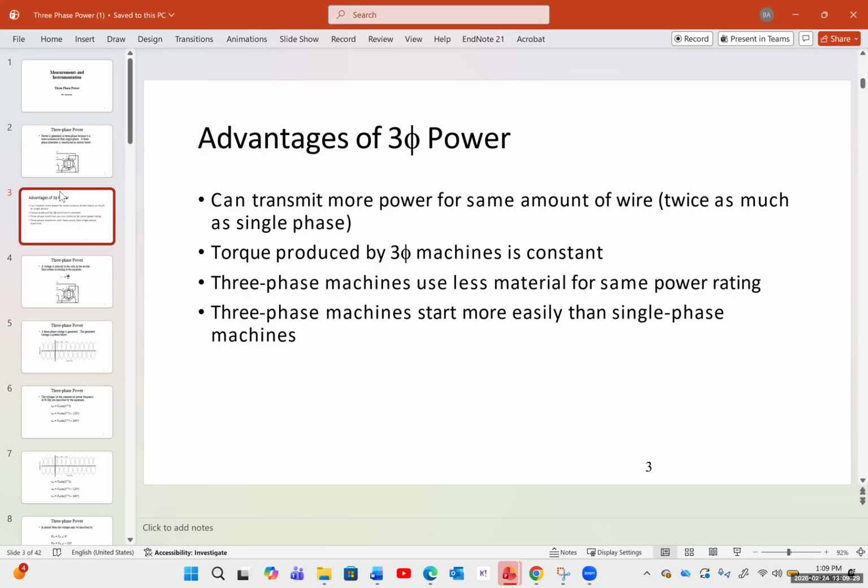So when it gets above 5 kilowatt, you most certainly need to go to a three-phase. Up to 5 kilowatt, they are probably the same price. But when it's over 5 kilowatt, it gets much bulkier and larger, and you most definitely have to go to a three-phase.